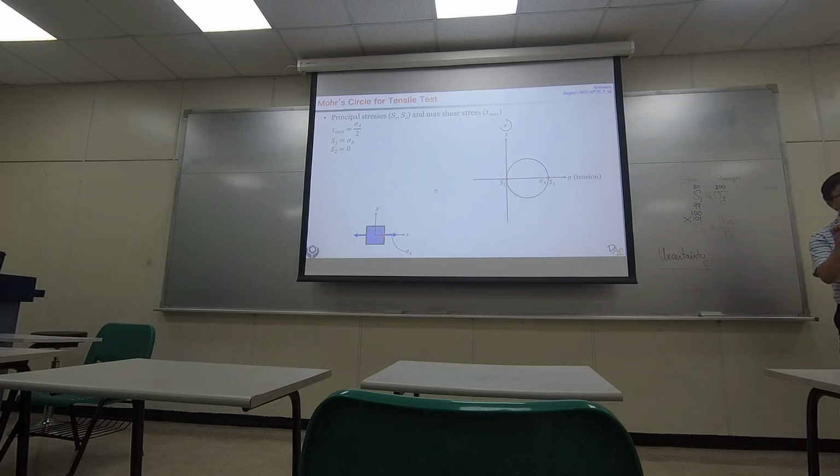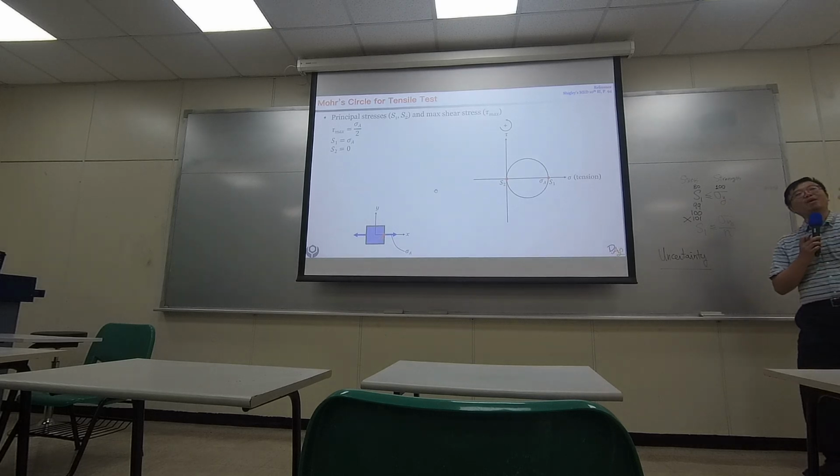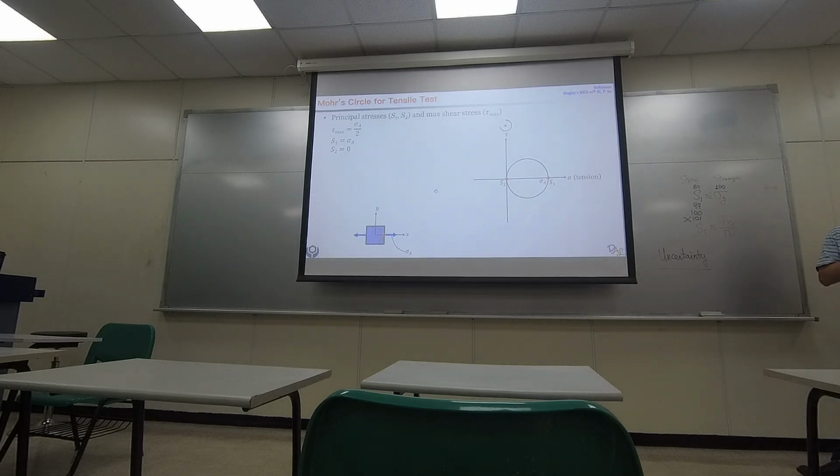So something that varies. If you get a value from Google, for example the Young's modulus of steel or of copper, it tells you a number. Does that mean the same material around the entire world has the same Young's modulus? Actually, no. Because that value from the internet or the textbook is probably just an average value. Someone did experiments thousands of times and then told you that, on average, the Young's modulus of steel equals this amount.